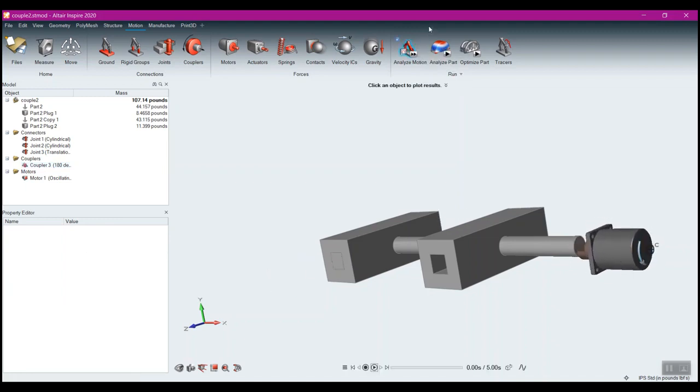So essentially, all you're doing is saying the behavior of one joint is going to be coupled to the behavior of another joint through this scaling factor, through this ratio. So you can imagine, if I had gears, I could set the rotation of one gear joint to be 360 degrees, and the rotation for the other gear joint to be 720 degrees, and effectively that would be a 2 times gear ratio.